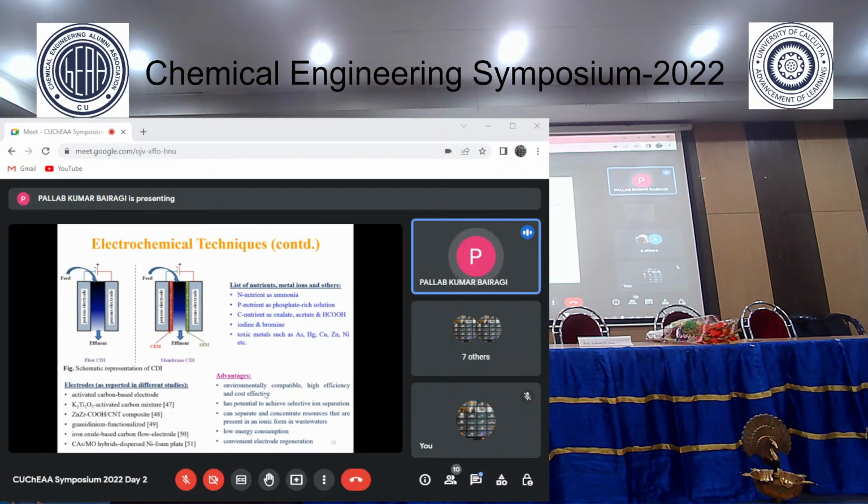Therefore, this method, on integrating with a suitable separation technique, can efficiently separate charged nutrients and help to recover maximum nutrients in addition to reducing salinity, in view of the circular economy. Moreover, the CDI method has been implemented in different studies for nitrogen recovery as ammonium. Ammonium along with other positively charged ions first transports through the ion exchange membrane and is adsorbed in the activated carbon-based cathode, where the ammonium ion deprotonates and converts to aqueous ammonia. It is then expected to be trapped in or within the cathode, resulting in an ammonia-rich solution due to the deprotonation of the ammonium ion via Faradic reaction.